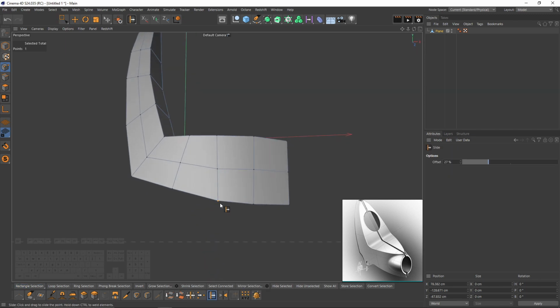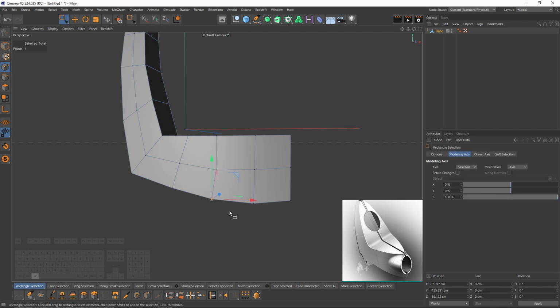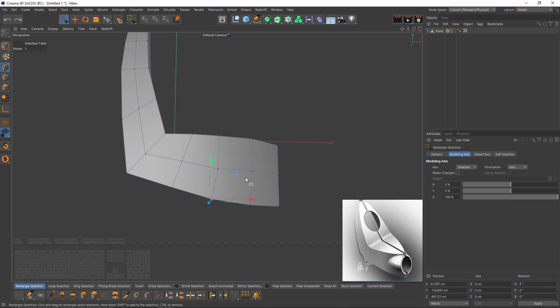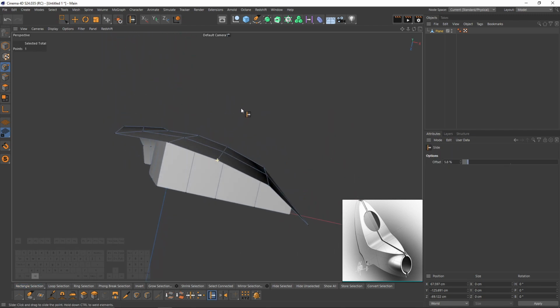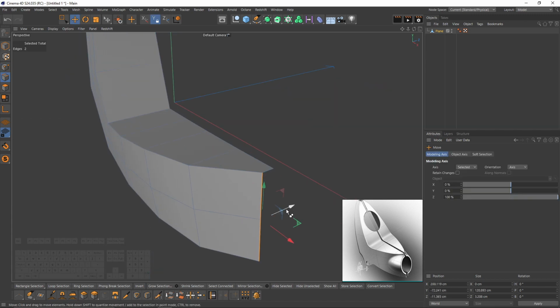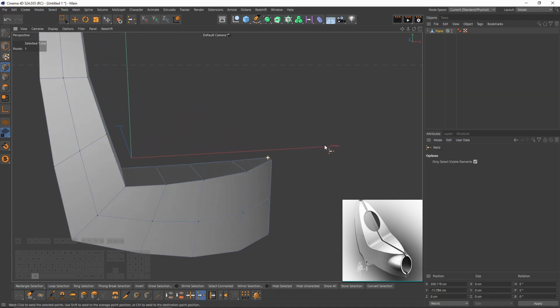Instead of moving, I'm gonna slide this. This is a safer move than moving this with the move tool, because we can break the smoothness of the surface. So anytime you have some kind of curve, try to use the slide tool. Now let's extrude these as well. I will set them to 0 as I did before. Now we need to weld these 2 points.